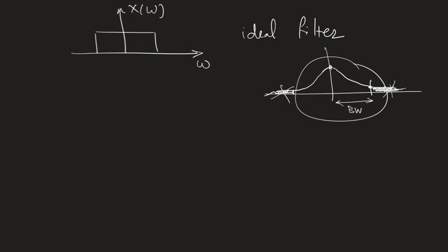Anyways, this is your voice signal, and then we said we want to divide this into 3 equal bands and deal with each one independently. Now, if I want to extract only one band, for example, this band only, how can I do this? I simply multiply my signal by this filter, right? Now we are dealing with frequency domain representation, so everything is a function of omega. So I multiply those two, and the result of the multiplication is going to be only this part of the signal, right? So only this part of the signal, only this part of the signal.